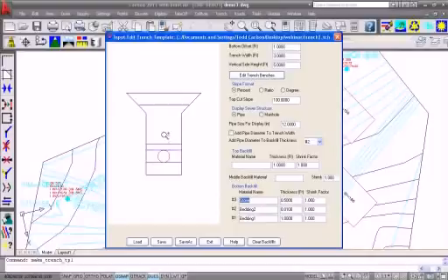Okay? And then, so what's really fluctuating is that these amounts are locked at the top, at the bottom. The stone is fixed. The middle bedding, bedding 2, is going to fluctuate as the pipe gets bigger or smaller. And then this middle here will fluctuate depending on how deep the trench is. So that's going to be our middle, this was gravel. That's going to be our middle backfill quantity, and we'll just call it fill.